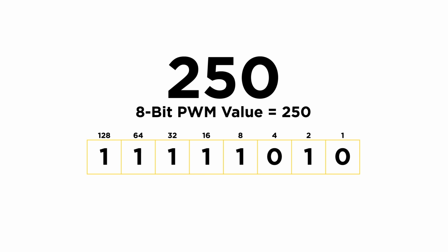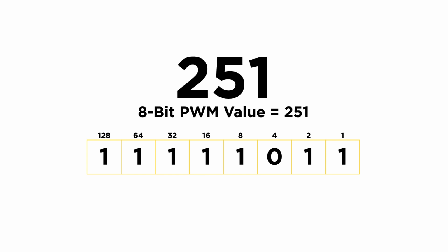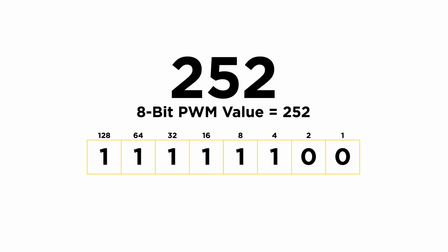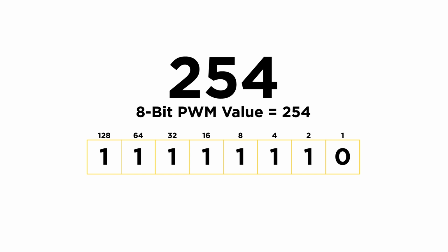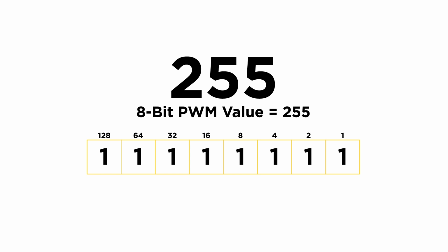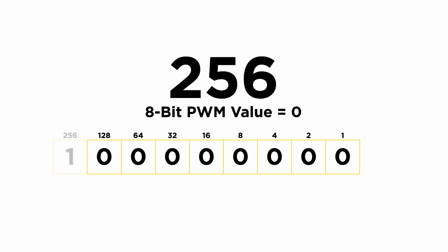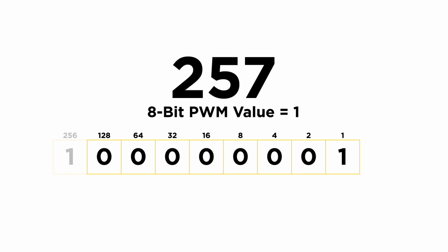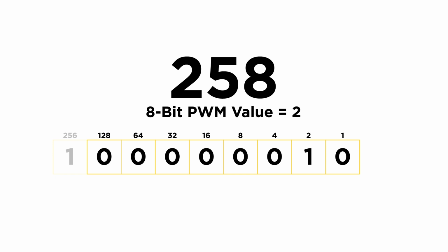So why is this happening? This has to do with how computers understand numbers. At the base level, computers understand zeros and ones. A number for the PWM is represented as 8-bit binary. The diagram shows how this is represented. In 8-bit binary, the highest number is 255. The next bit would be added to the left and is 256. The Arduino ignores anything over the 8 bits. So while the number in the serial monitor might show up higher than 255, it effectively starts counting back at 0.